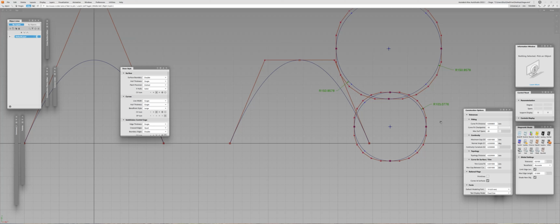There are a lot of reasons for that. Even though that spans, if there are a lot of spans, they can actually add discrepancy on the edit points, these vector values, because if it is really, really cramped, there is just not enough lead-in, not enough scale for the tangency and continuity to spread itself too much. It can be very confined, and that's why you get these kind of small irregularities in the surface.